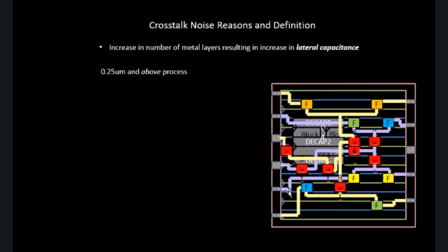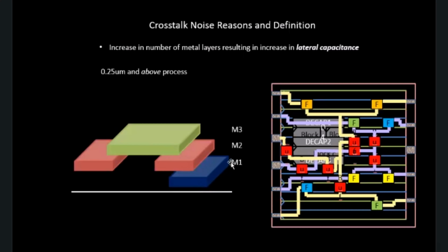So now in this case, the number of metal layers that would be required to get a connection, for example, from this point to this flop point, will be very few. With a single M1 metal layer, you can directly connect from this point to this point. With a single metal 2 layer, you can connect directly from this point to this point, and again use the same metal layer to connect from this point to this point. Okay, so this was the scenario a few years back. Also the width of the metal that you see is quite huge, and that actually helps in reducing the resistance. So higher the area, lower the resistance, R equal to rho L by A. So that was the reason for having wider metal and very few metal layers that help us enable this amount of connections.